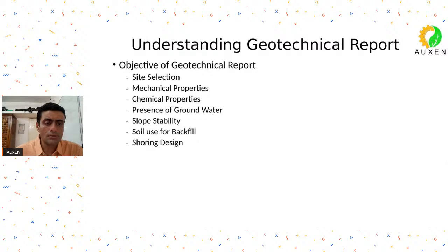A geotechnical report, of course, will help you in understanding the mechanical properties like bearing capacities, and properties like C, phi, SPT values, and shear parameters. I already told you shear parameters C, phi. So for finding out these properties, a geotechnical report is required. That is an important objective of carrying out geotechnical testing.